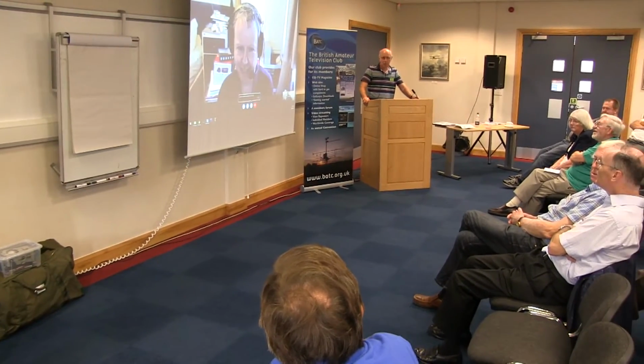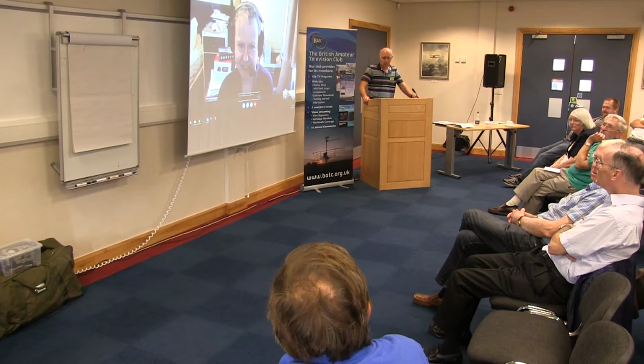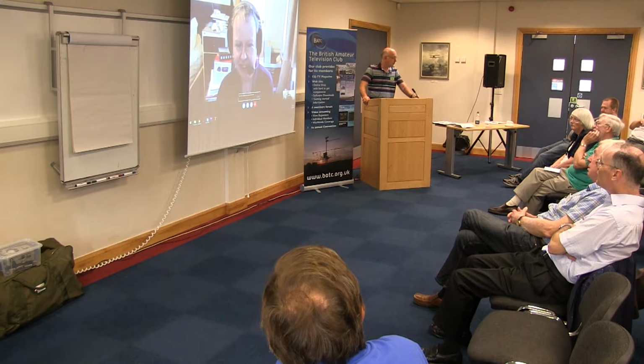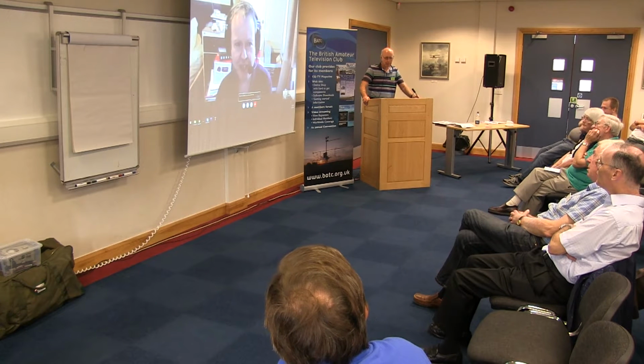Sorry, forgot to mention. Pilot tones on DVB-S2. Yeah. Should we be running them, or does the receiver implementation need to be there as well? Well, it depends how the receiver's been implemented.